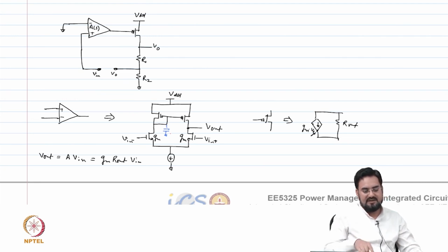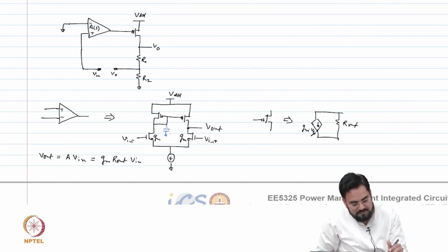Okay. And when we have a second stage PMOS, then this output cap will become more dominant, because you have a very high value resistance. So, this is mostly considered as a first order system, because the moment you have the PMOS connected at the output of your differential amplifier, that becomes the dominant pole, and this first pole, which is coming due to this cap, becomes negligible.